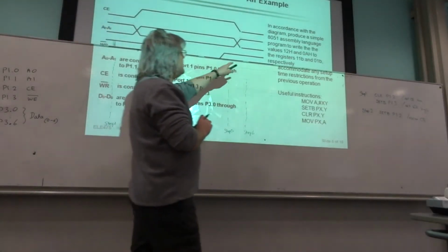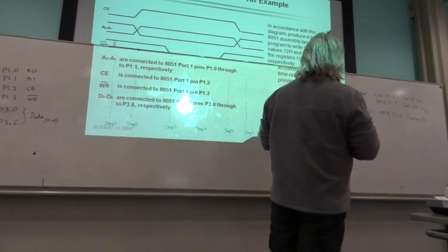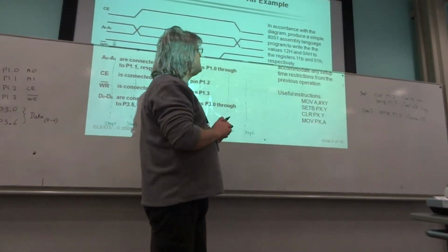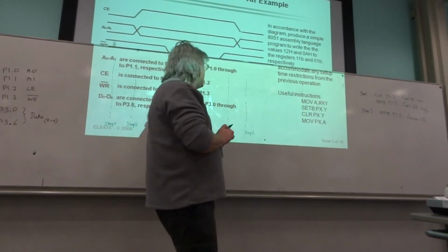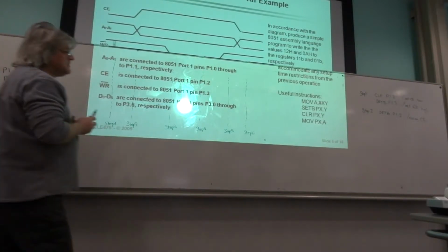To know what the valid value is, I've got to read what I've been told up here, and it says I've got to write in sequence, first of all, the value on the data bus 12 to register 1, 1. So the address value is 1, 1. And this is the address bus. Now I could do this individually a bit at a time, or I could write, well, I can't think of a better way of doing it, so we'll do it a bit at a time.